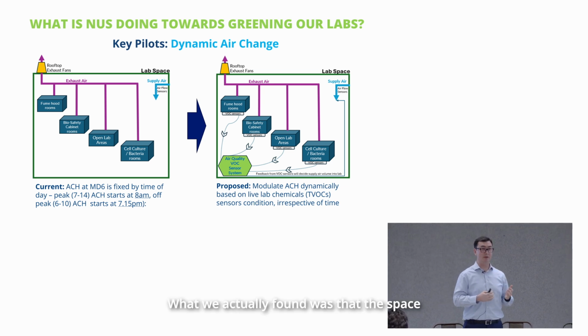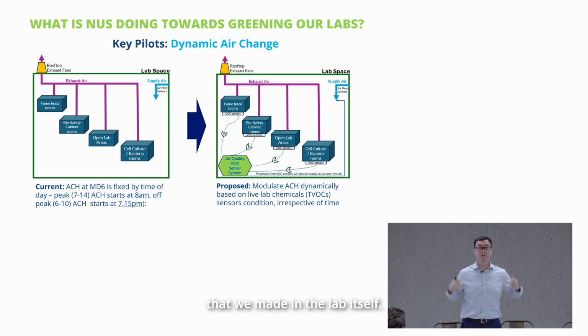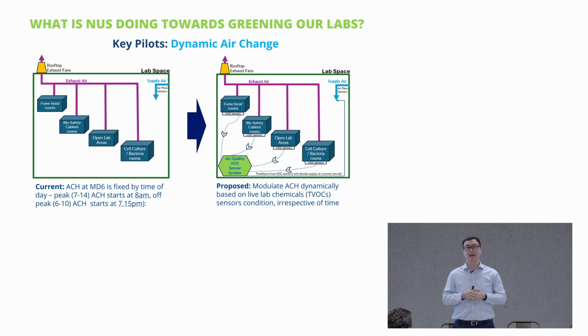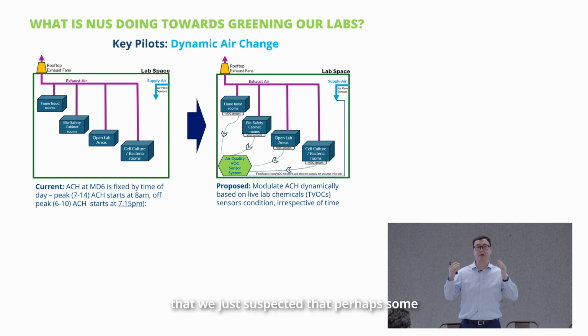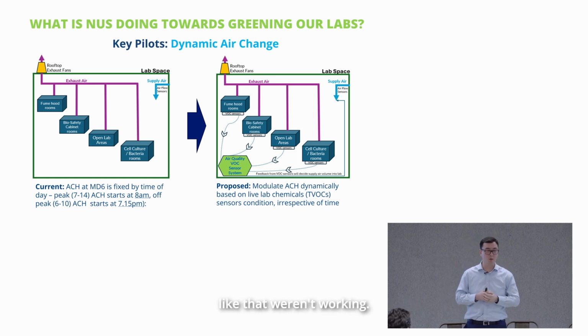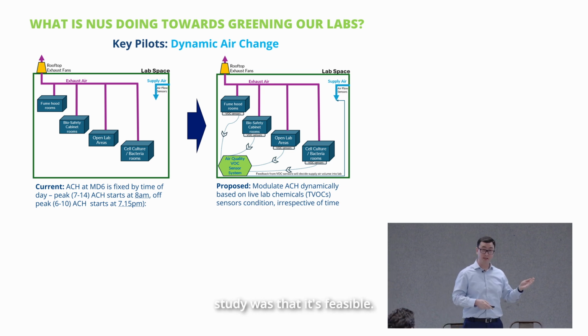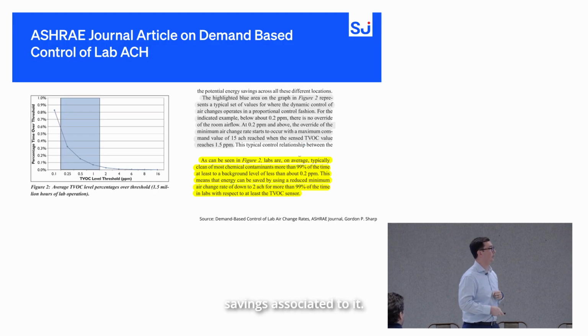What we actually found was that the space was completely overcooled, and that aligned with the observations we made in the lab itself. People were wearing coats, and on top of that, they had their lab coats on. In some cases, the room was so cold that we suspected perhaps some of the reheat coils and things like that weren't working. But the conclusion of the study was that it's feasible, we can keep the space comfortable, and there are energy savings associated with it.